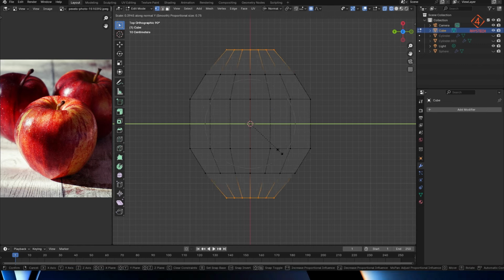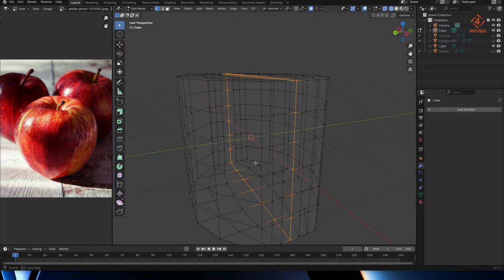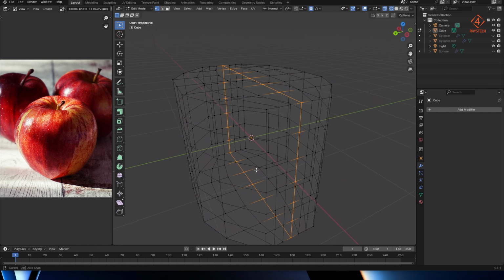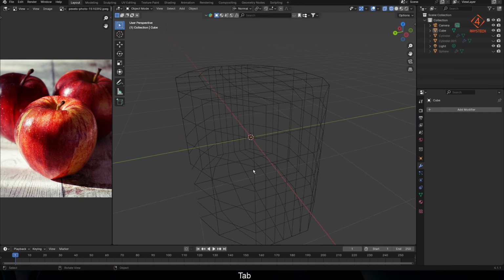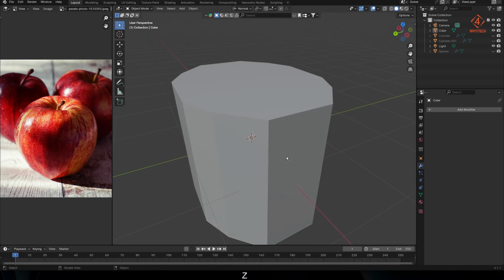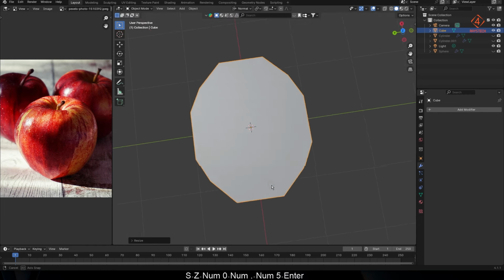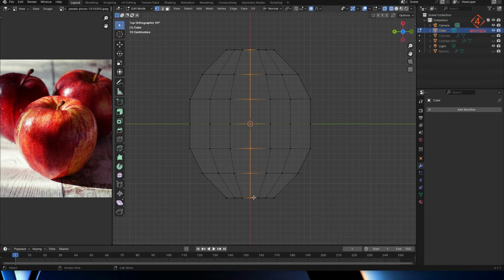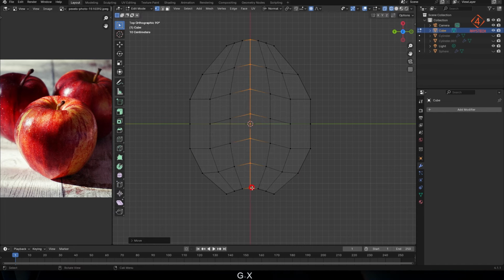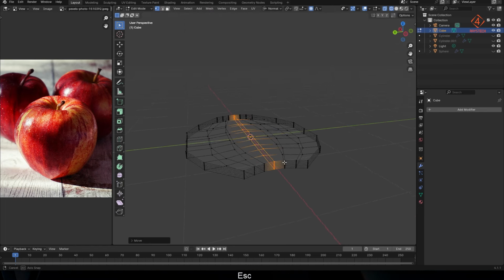And then once again I'm scaling these vertices down and using the wheel to enlarge or scale down the area of effect. Now we've got it selected top to bottom, we've got a rough shape of a leaf, and let's reduce the height of this thing a bit more. Something like that is enough. Yep, that looks about right. Let's select these vertices, move them up. Still I've got my proportional editing on. Keep that in mind.